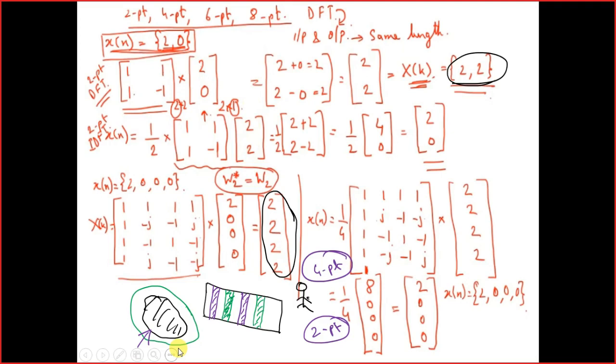However, if your signal is a good quality signal, and then by zero padding you are increasing the signal length, then it can help you in observing the frequency spectrum with a higher resolution. So if you have a higher signal length, you will be getting a higher resolution.